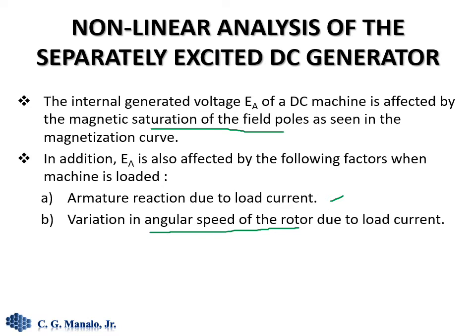And in fact, if you don't have a speed regulator, the change in speed becomes severe, so that it greatly affects the terminal voltage of the generator.